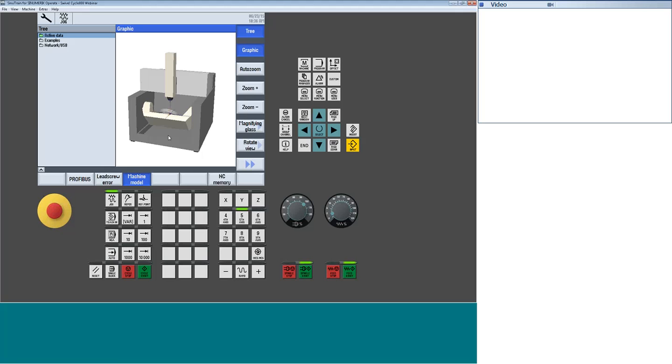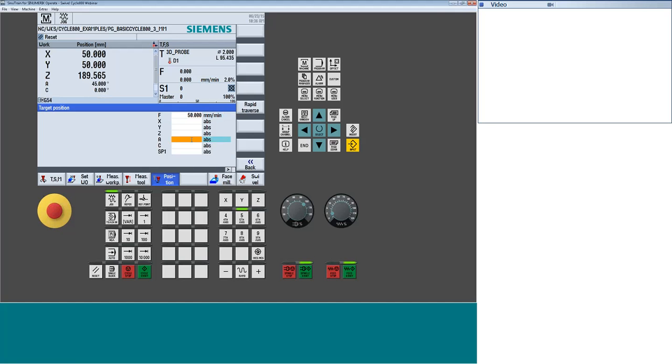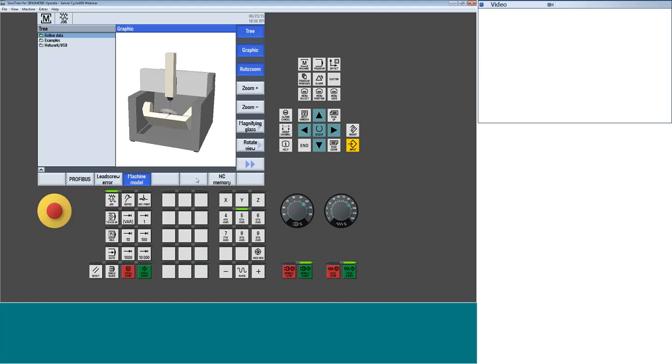You'll notice when I revolve the A in a positive direction, the trunnion in this configuration tipped up towards me, towards the operator. If I was to go back and define a negative, which you can go in either direction, now the machine's moving over. I left it in feed, so I'll just crank up my speed. Now I'm sitting at a negative. You see the negative right here next to the A. If I come back over to my machine space, I see that the A is now tipped up at some new position. These are positional moves, obviously based on the machine coordinate system.